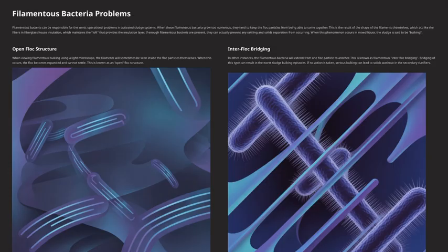Filamentous bacteria are also involved in foaming issues. While foaming is often associated with fats, oils, and grease in the influent, some filamentous bacteria have evolved to be buoyant. They float to the surface and directly contact these fats. When a large amount of grease enters the aeration basin, these bacteria rapidly break it down, and that process often results in foam formation. This foam layer can become a persistent problem, impacting the overall treatment process.